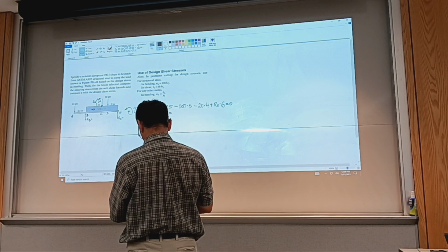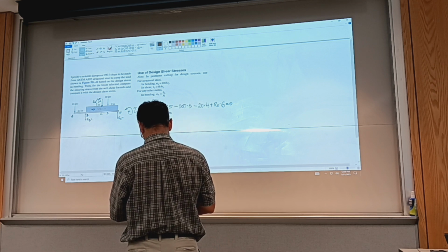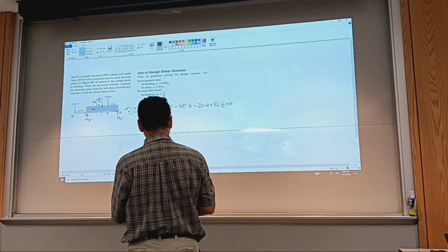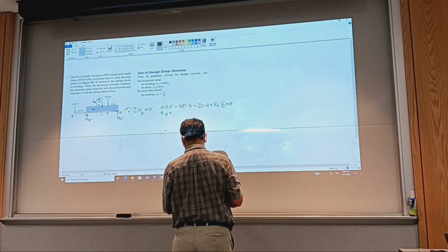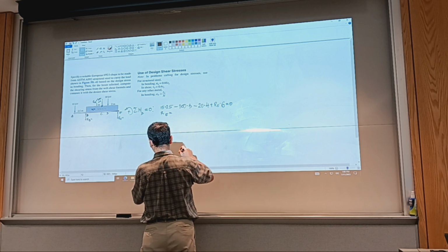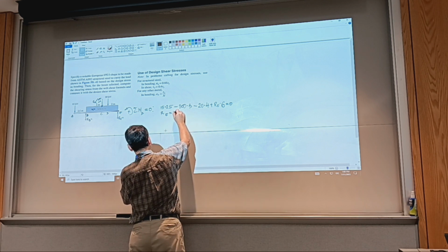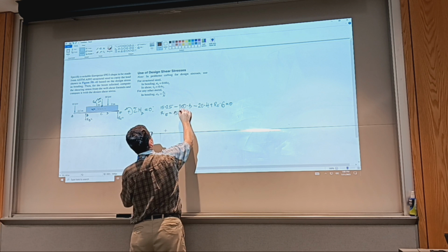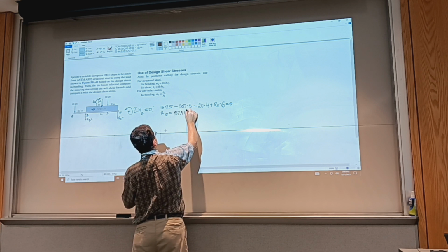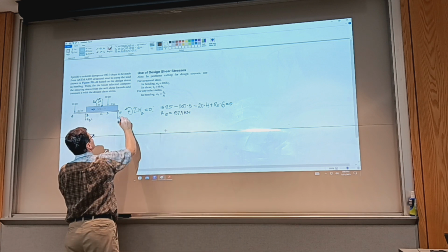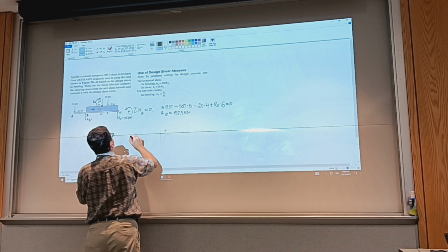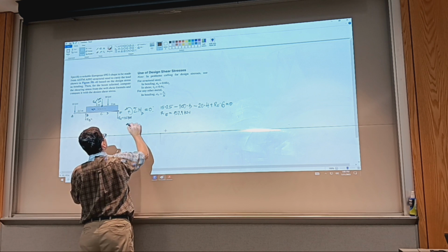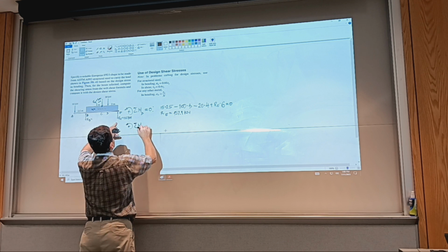So 15 times 2.5, negative 300 times 3, negative 20 times 4, over 6, equals 157.08, I'll say 157.1 kilonewtons. Let me put it here. So 157.1 kilonewtons. And then I'm summing moments about point E.